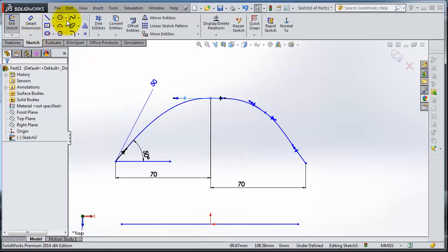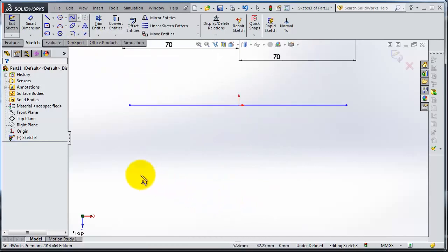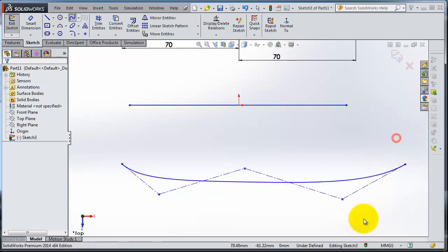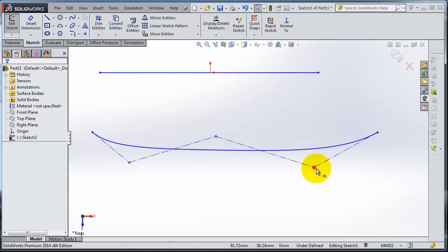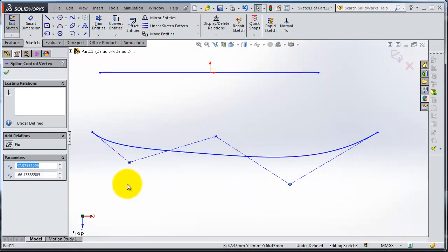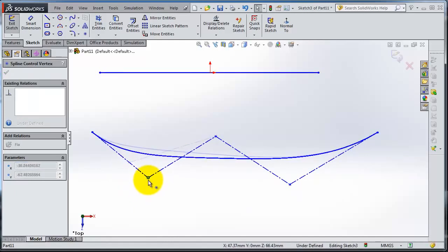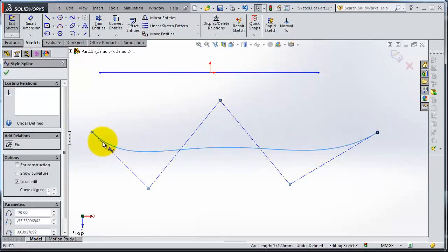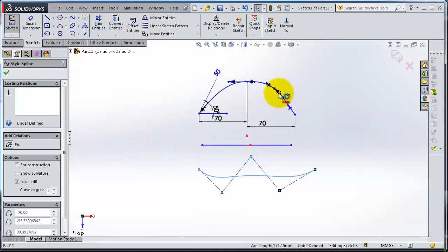And now you have a second type of spline, with guiding lines as a way for more control of your spline. So you notice your spline is contained inside these guiding edges or lines. So if you select that point, from that point you are able to control your spline. So as you notice, you don't have the handle and the size as shown in the previous type of spline.